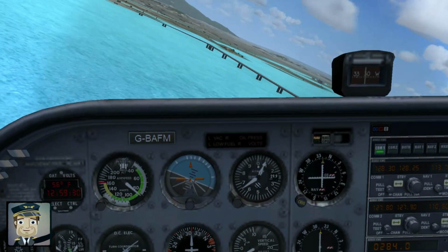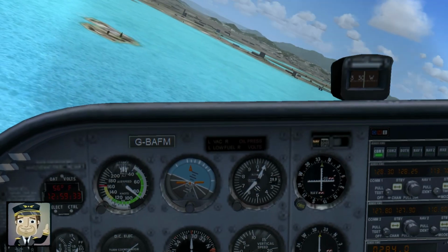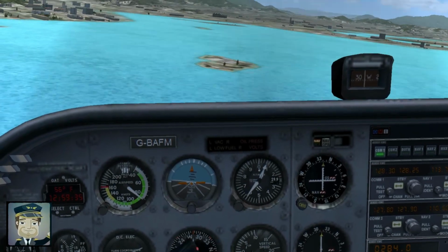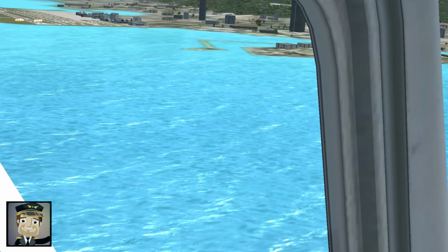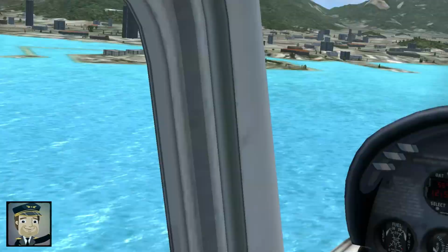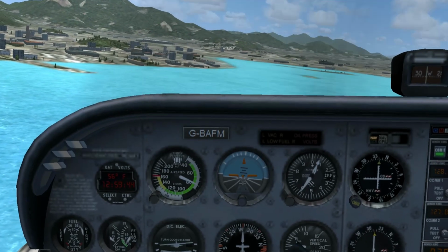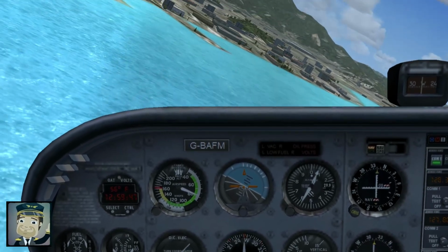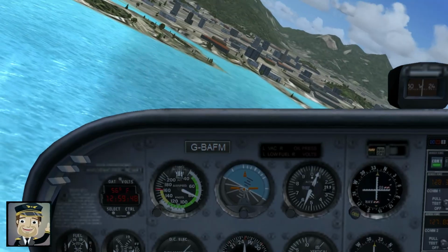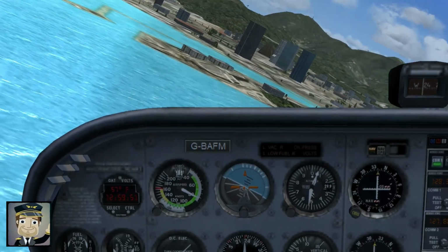During this segment, the pilot verifies all critical landing items: proper flap setting, landing gear down, speed within limits, and confirmation that the runway is clear of traffic. It is a last chance to ensure the aircraft is fully stabilized for the approach. When the airplane reaches a proper alignment point, the pilot begins a smooth, coordinated turn toward the runway's center line, and into the final leg, also known as final approach.